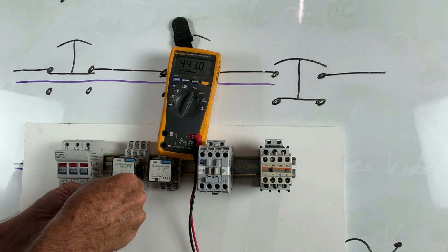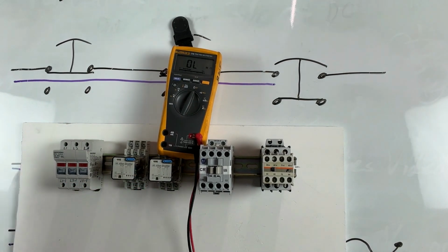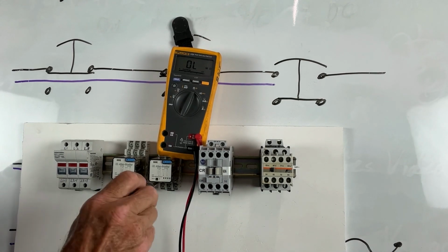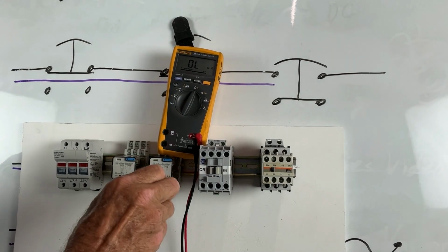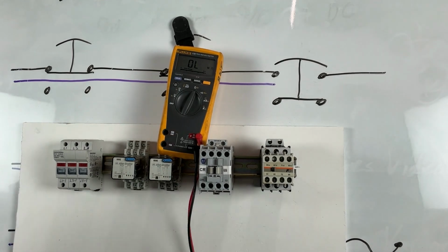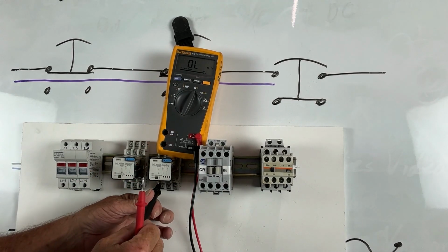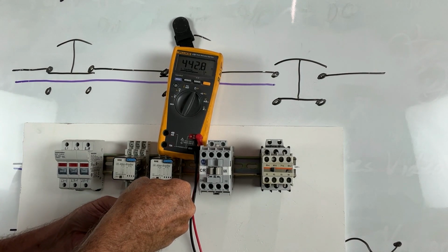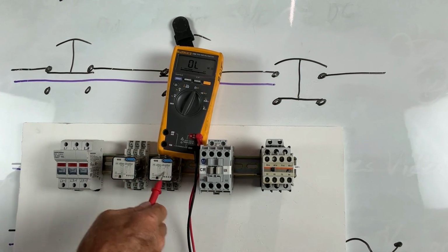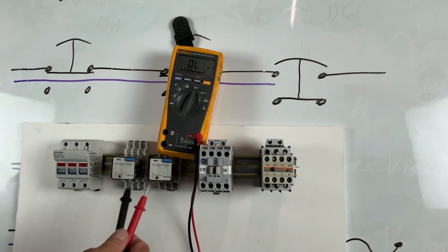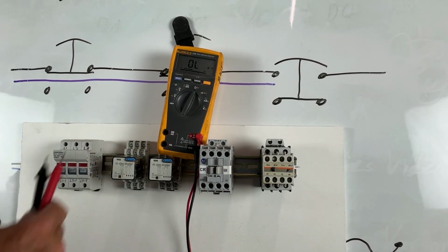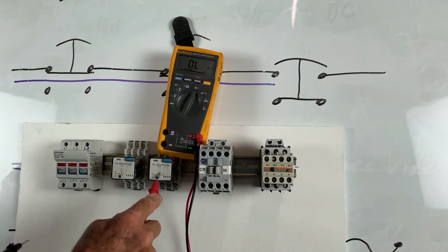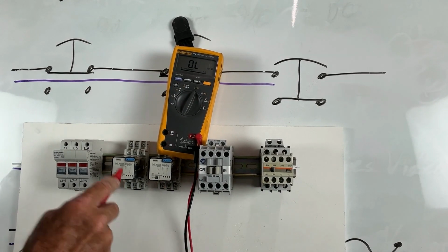That one's 443 ohms across that coil. Now, we'll go ahead and tighten this one up. So that's something to always keep in mind when you're checking things: make sure you've got a good connection with your probes. And see, that's 442.8. So these are measuring really close to the same, so that'd be a comparison. So if this one wasn't working and you measured, say, like the 90 ohms like you did over here on this one, and this one measured 442 and this one's working and this one's not, you would know that that's bad.